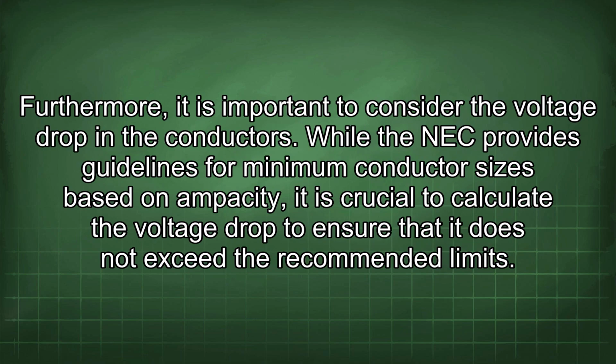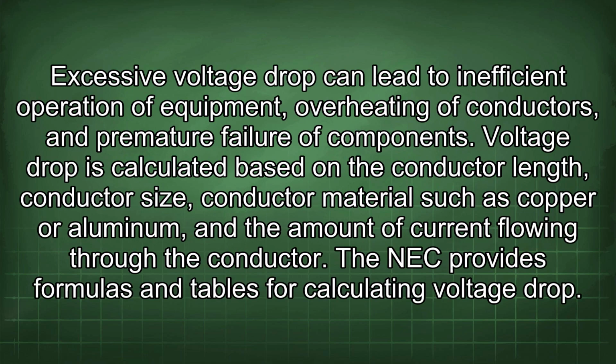Furthermore, it is important to consider the voltage drop in the conductors. While the NEC provides guidelines for minimum conductor sizes based on ampacity, it is crucial to calculate the voltage drop to ensure that it does not exceed the recommended limits. Excessive voltage drop can lead to inefficient operation of equipment, overheating of conductors, and premature failure of components.